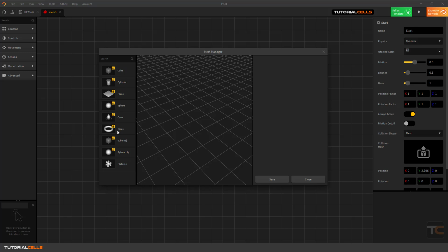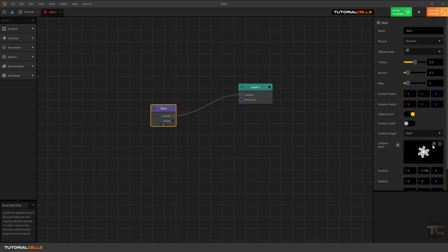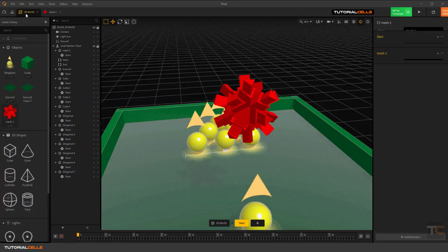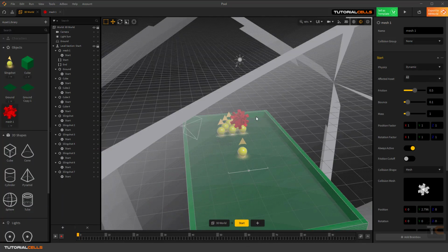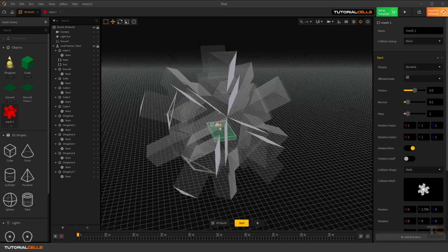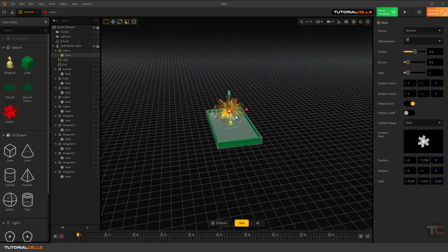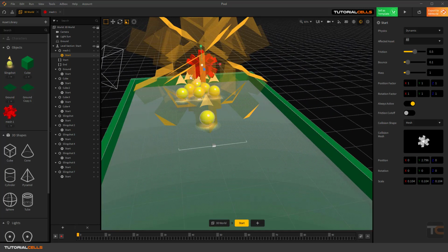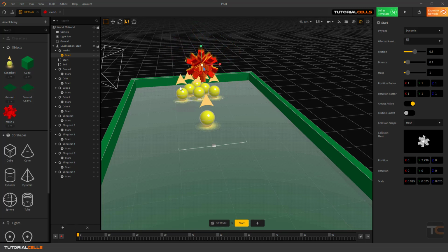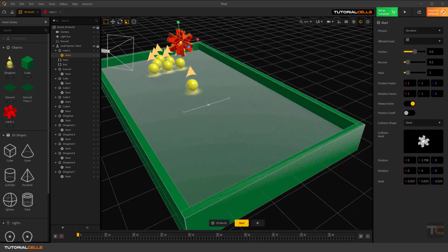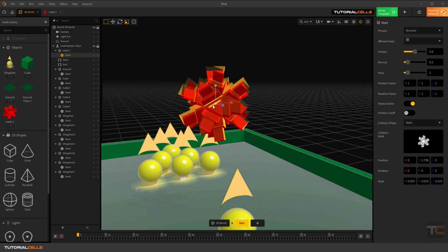We have lots of objects that are seen, and this is our imported mesh. You can tell the software, okay, give my collision shape exactly like my mesh. You can select your mesh inserted here. Boom. This is our collision shape. Going back to the object, turn on the collision shape, and it is much bigger than your object. You can select it and simply uniformly scale it to fit your object. Nice. And now our collision shape is exactly like our object shape.